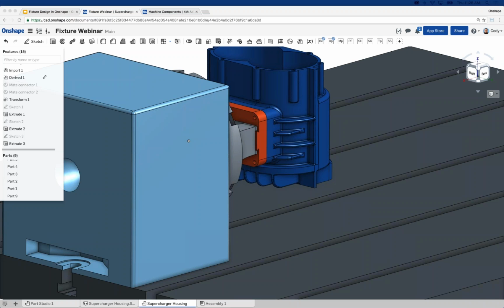Questions? Can I offset from a sketch plane, adding a gap on the back side of the pocket? Absolutely. There's two ways you could do that. You could, of course, insert an offset plane and sketch on that. But you can also do what we call a two-direction extrude. It's very similar to the offset from option in SolidWorks, if you're familiar with SolidWorks. Essentially, you're going two directions. I think most commonly users would insert an offset plane.